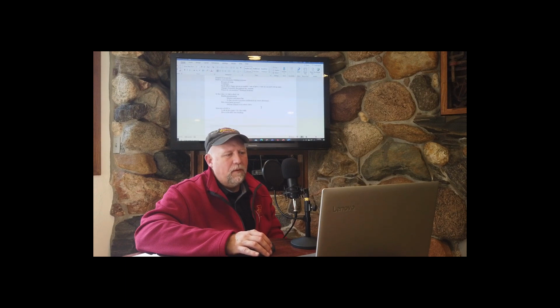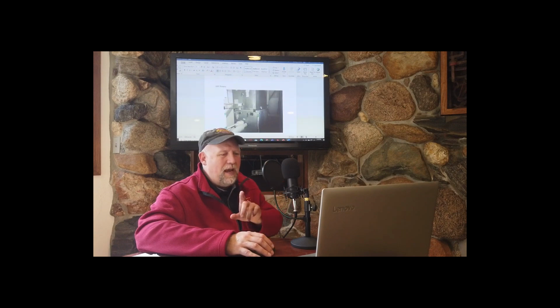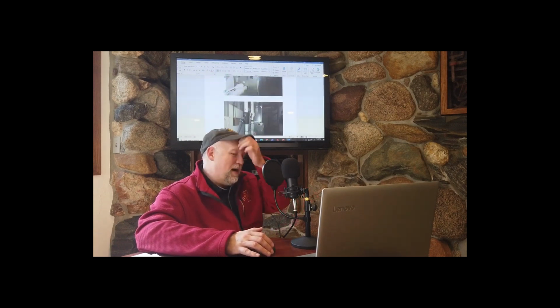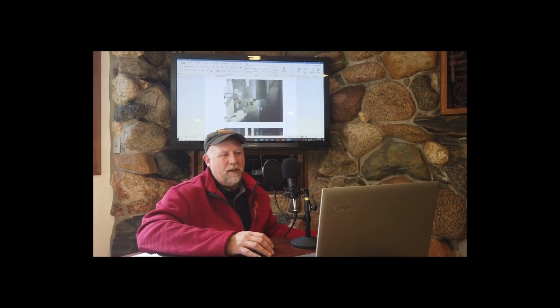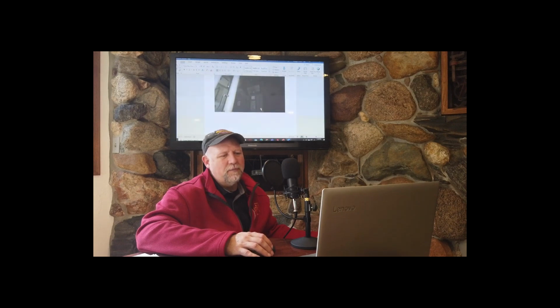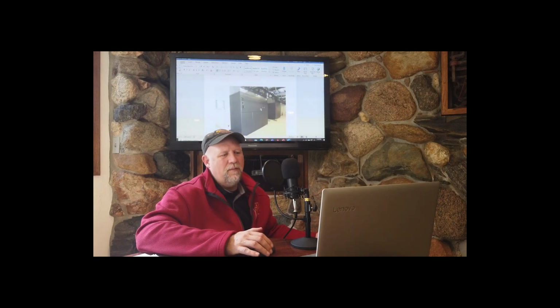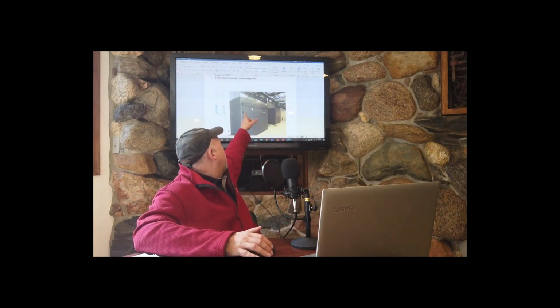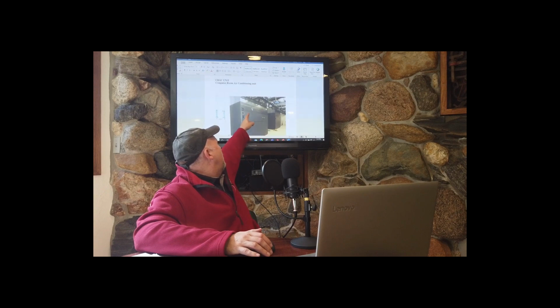Okay, let's go back here. In the handouts, I've got a bunch of different pictures of air handlers. The thing is, notice, they all look like galvanized steel boxes. It's really hard to see very much from these, but I put some small ones, some larger ones. This is a specialized one for a computer room unit. This is a raised floor. The return air comes through the floor. It cools it in here, and then see this ductwork in the ceiling.